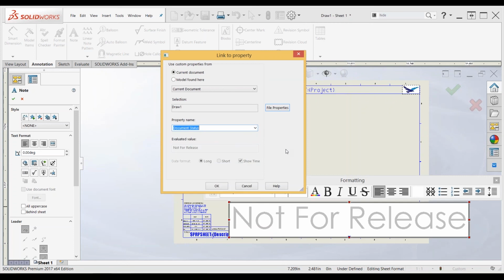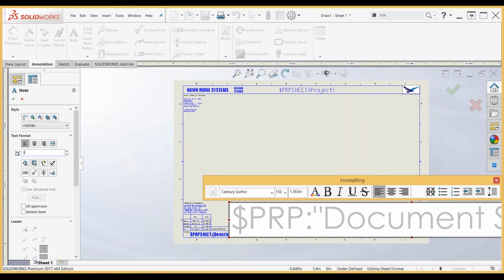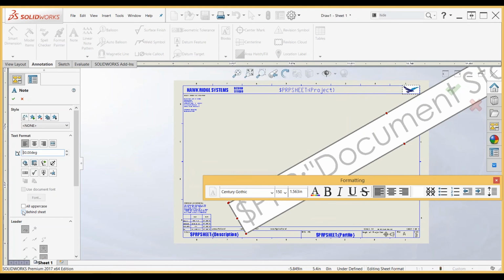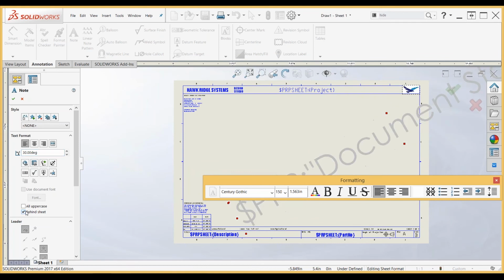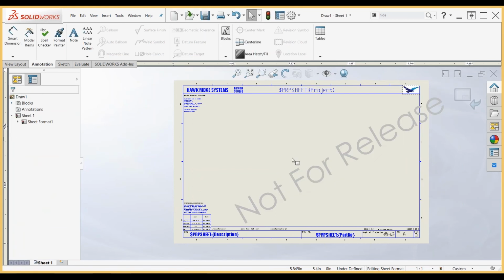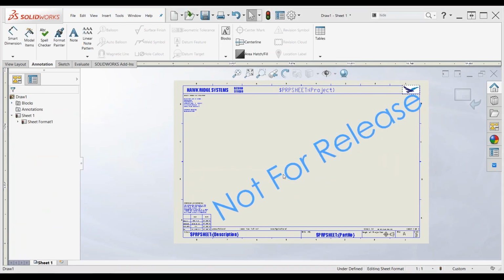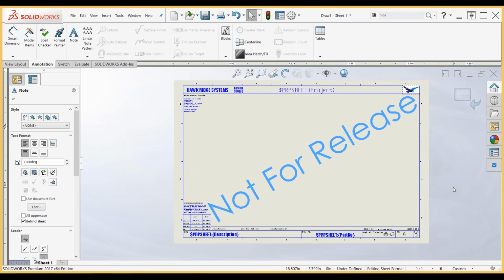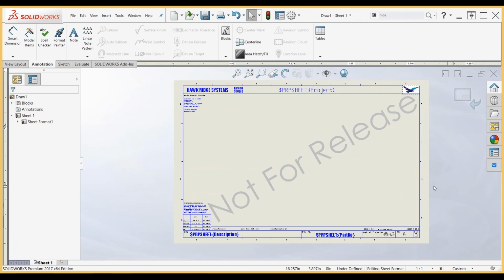So just hovering over some sort of vertex, right-clicking on it, and going down to set as anchor, you have a list for which table you want it to be. So right under my logo here, I'm going to lock that to bill of materials. That looks good to me. And down here in the bottom right, I'm going to grab another vertex, hover over it, right-click on it, set it as an anchor point, and this will be my revision table. So now I can easily snap those tables to the locations that I want them to be.